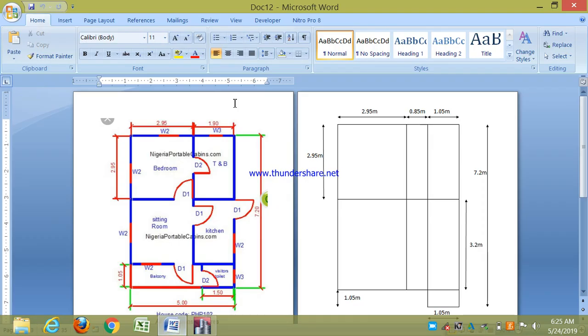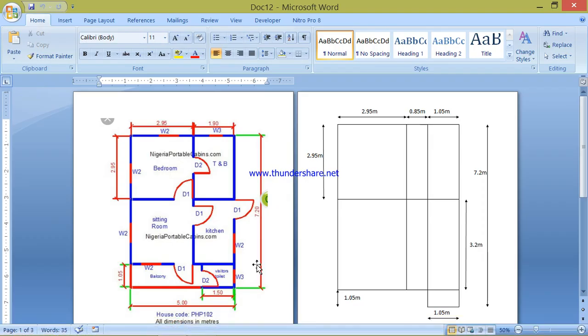Now let us consider this as an example. This is a plan showing the center to center distance between the walls. For this plan, I need to form a grid system like this. If you take this as an origin, wherever they have constructed a wall, we need to place a beam over it. Therefore here, here, here and here they have constructed a wall. Means in these lines I need to form a grid system.